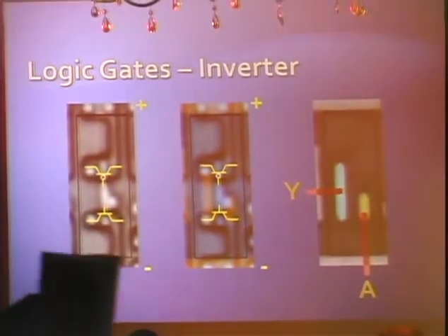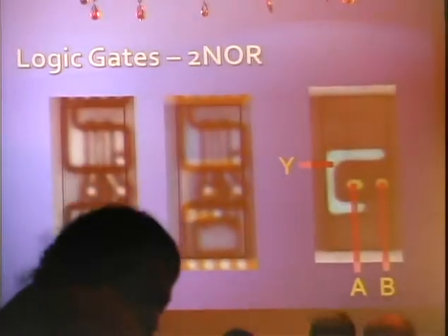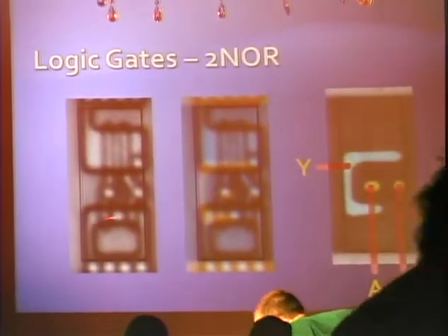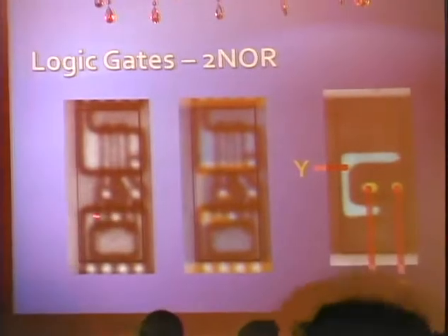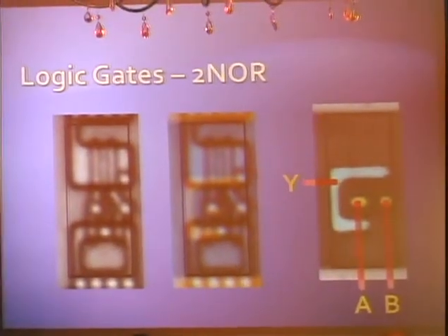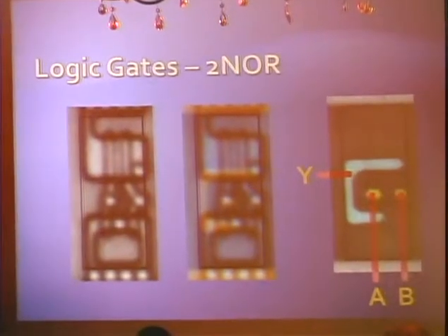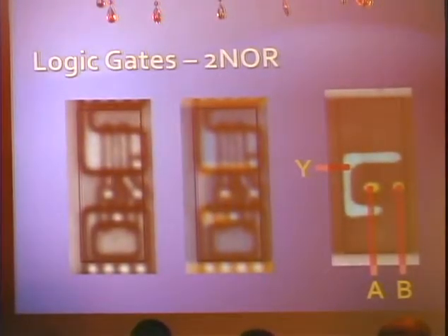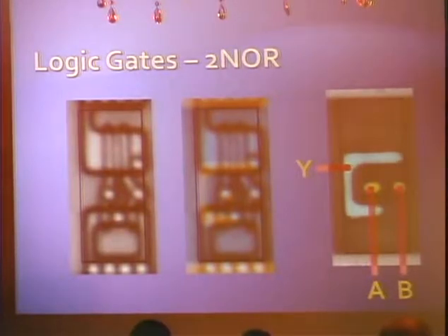This is obviously the smallest possible one. More complicated gates would have 2 transistors on each side, and this one, for example, has the output in the middle. So if either of these buttons is pressed, it will connect to ground. So it's a 2-input NOR gate. By following this, you can figure out any gate's functionality, and actually they look very structured. The 3-input NOR would just be the same but a little wider and so forth.